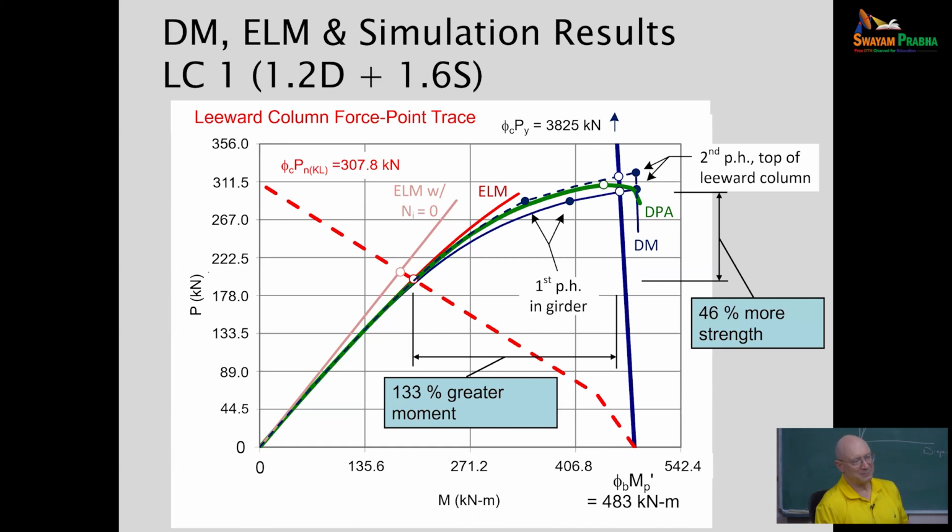So in the direct analysis method, although we are not explicitly talking about the plastic hinges, we are indirectly relying on the plastic hinge capacities. Yeah, I'm kind of glossing over a lot of things. Again, as I said yesterday, my aim was to go relatively light with the direct analysis method, but tie it in with Eurocode, and so I've just made the comments about that. Sorry, I lost my train of thought. Tell me your question again. So we are not explicitly talking about plastic hinges in the direct analysis method, but indirectly relying on that. Yes.